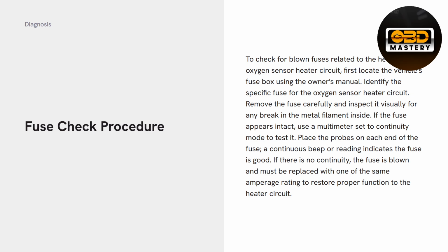However, you're going to want to make sure that it is intact and it is not fried, and it looks like a hair, very faintly visible. So if it's black and it looks like it's burned up and the fuse just went bad, then it is definitely time to replace it with another one, and ensure that it has the proper amperage rating. So you may even have a 5 fuse, so just make sure the fuse that you take out is the same one and it is rated for proper function.